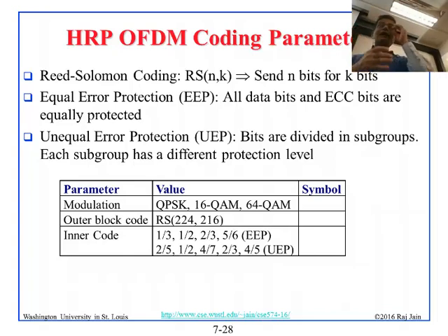Or in the case of video in particular, if you lose the last bit of a word, it doesn't make a difference. The color is, let's say, 9, and you make it 8, it will not make much difference. So the first bit is much more important than the last bit. If you change the first bit, the color is 8 and it becomes -8, it will look odd. So the first bit is more important, so they use unequal error protection.